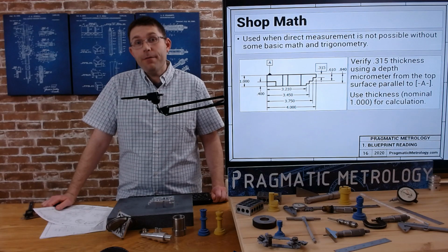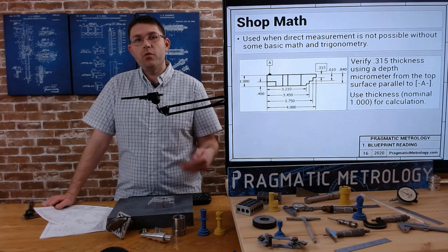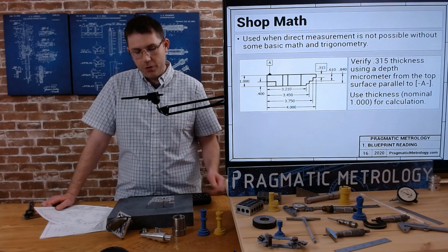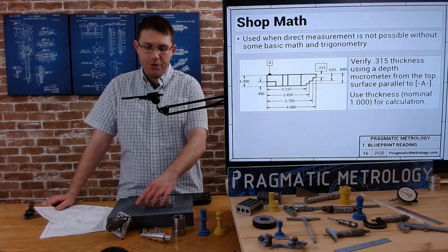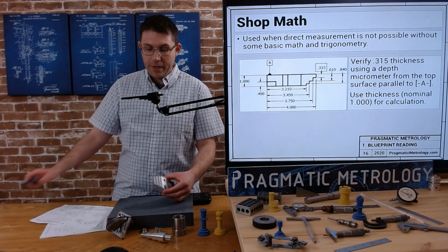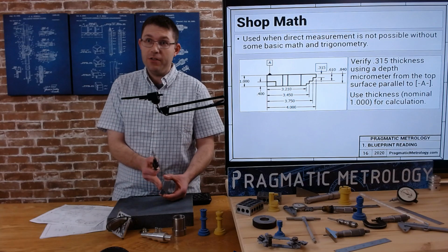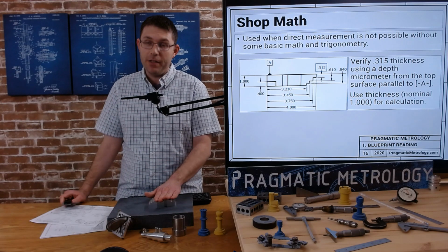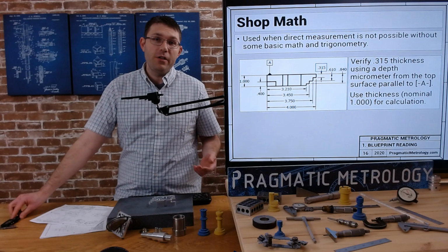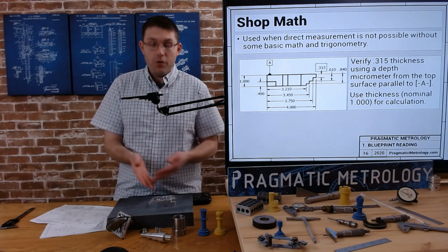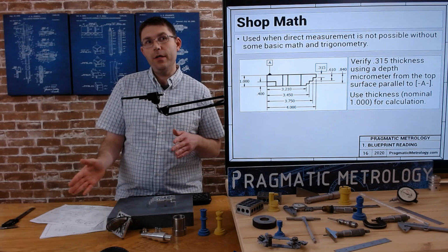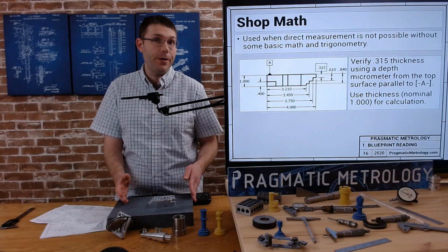Now you want to verify operation 1's work. First article of operation 1. There's still a piece of uncut material on the backside, so you can't verify anything back here. It's still in the machine and it still has extra material. So you're going to have to come off of the top and try to verify each step. Now, because this part is in process, these are all reference checks, but you can still use the shop math to know if you've already made a scrap part or not.